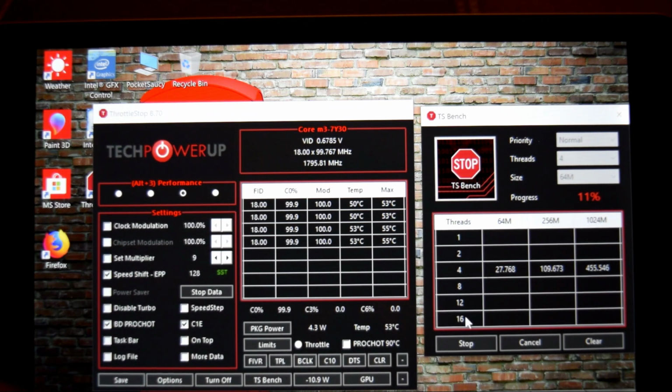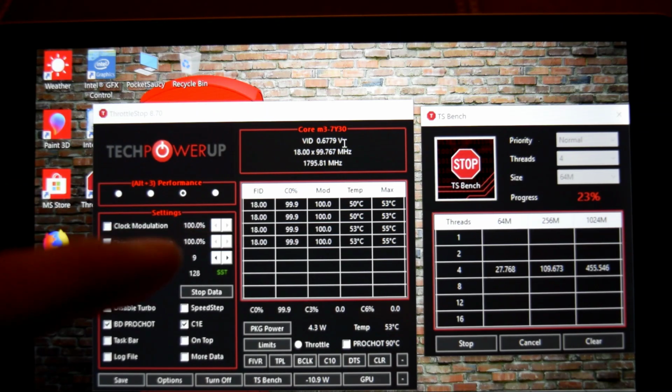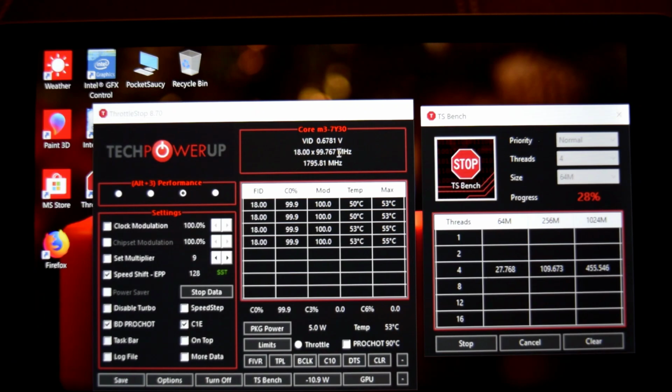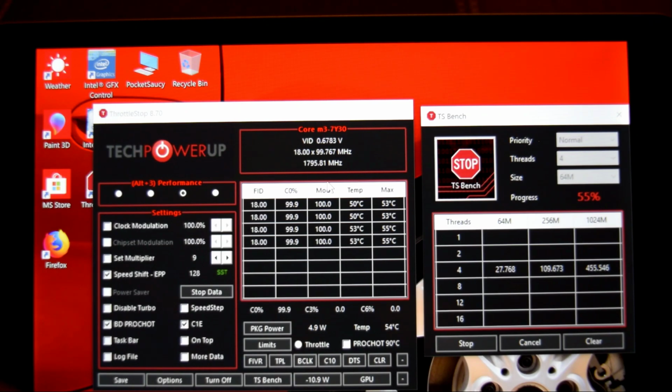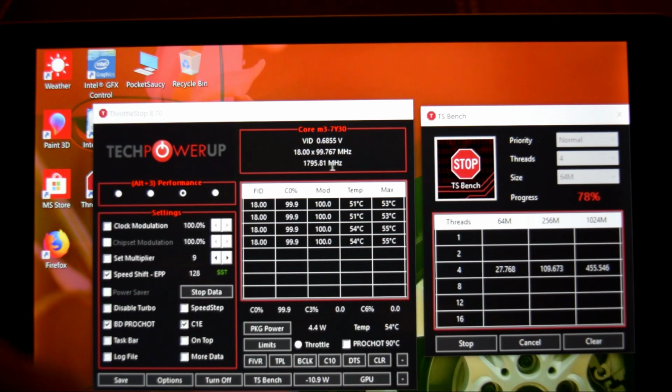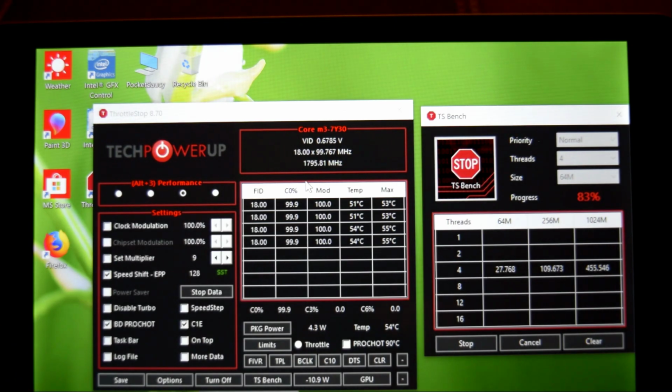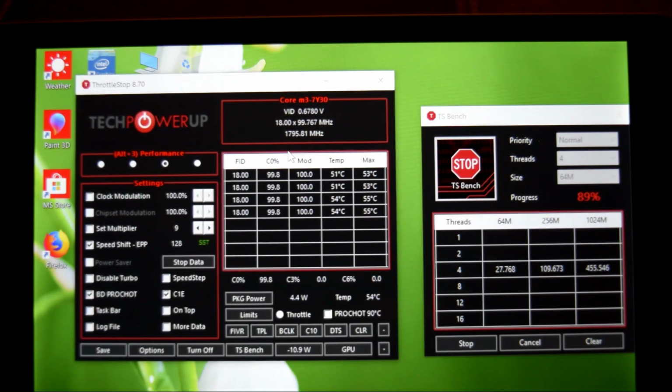So you can undervolt the GPU and the CPU. They both will take less power, less electricity. So if you want to unlock the TDP, this means that you can achieve a higher wattage and also achieve more performance out of that wattage. Or if you want to save power, you can stay at 4.5 watts but still have a much higher frequency than the base frequency they give you at first. So overall, there's a massive benefit to doing this.